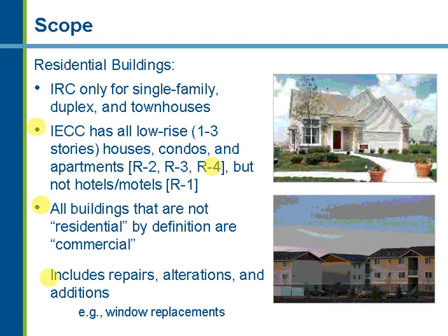One example of that would be if you're installing storm windows over an existing fenestration, then you're exempt from meeting the requirements of the fenestration as though it was new construction. Another example of an alteration would be construction where the existing roof or floor cavity is not exposed and you're doing some sort of alteration. If you're not exposing the cavity that has insulation in it, then that would fall under an exemption. There are several other ones that you can go out and look at in detail.